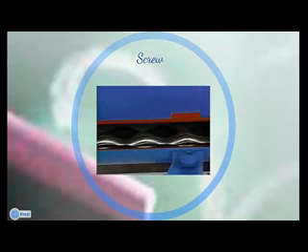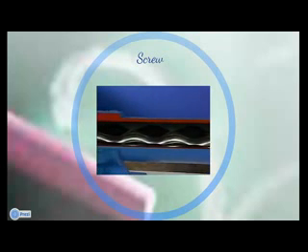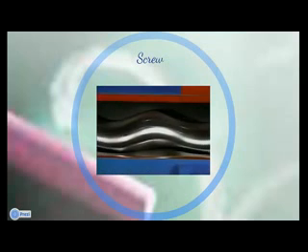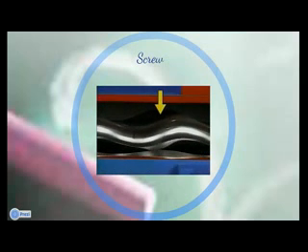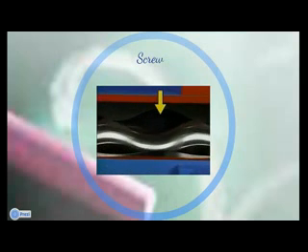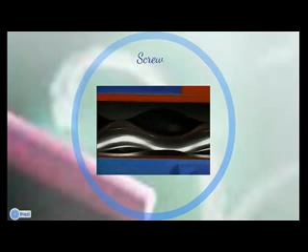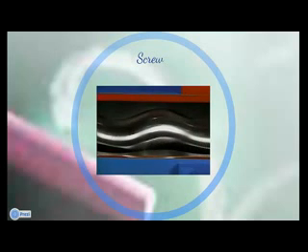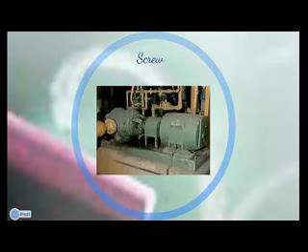The screw or rotor is located inside a casing, and it's connected to a driver. As the screw rotates, cavities form between the casing and the screw. These cavities move or progress toward the pump's discharge as the screw rotates, carrying the fluid along.